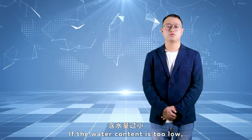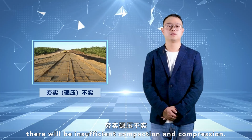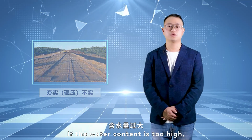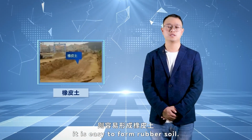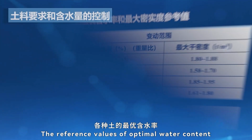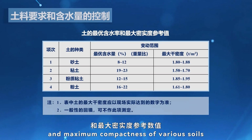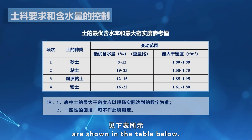If the water content is too low, there will be insufficient compaction and compression. If the water content is too high, it is easy to form rubber soil. The reference values of optimal water content and maximum compactness of various soils are shown in the table below.